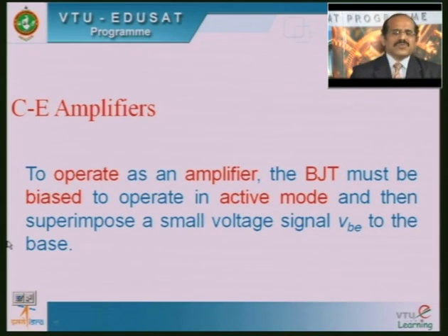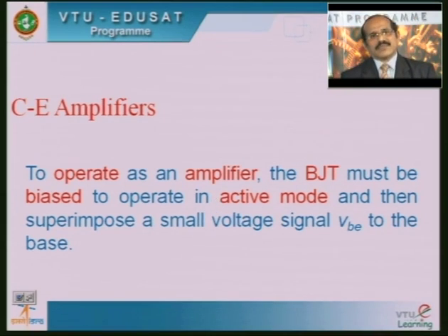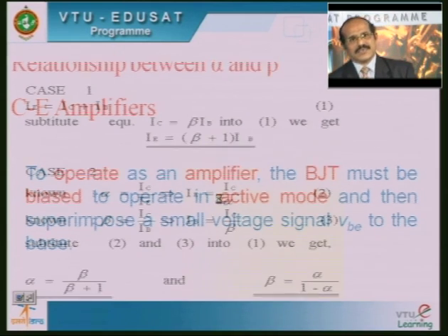And you know that usually to operate a BJT amplifier, we prefer the common emitter configuration. It is only because this will provide more current gain as well as more voltage gain. Also, it should be noted that to operate the BJT as an amplifier, we make use of the active region, where the output characteristics are linear and there is equal distance between the neighboring curves here. Which is very important as far as faithful amplification is concerned here.